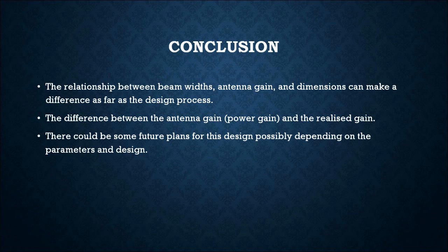I also think that this design could be added on for any future plans, because it really depends on the parameters that you're given in the design. At times, lower frequency radars, in most cases, not all cases, will have bigger transmitting antennas compared to mid-range frequency radars in order to get narrow beam widths. So knowing the parameters and the designs and what you're trying to achieve is critical for any future plans for this design.